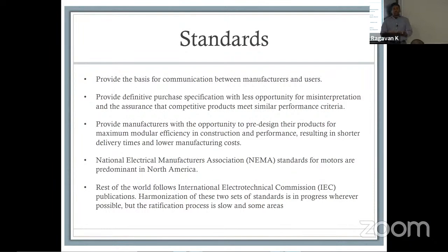That brings you to the question of enclosures. We will talk about enclosures, because you have to know not every motor works everywhere, right? If you have made mistakes of that kind, including with light bulbs, placing what's supposed to be inside the house outside, you will find out very quickly they don't last nearly as long as they should.